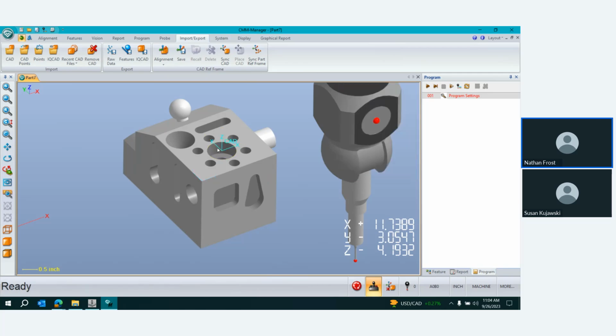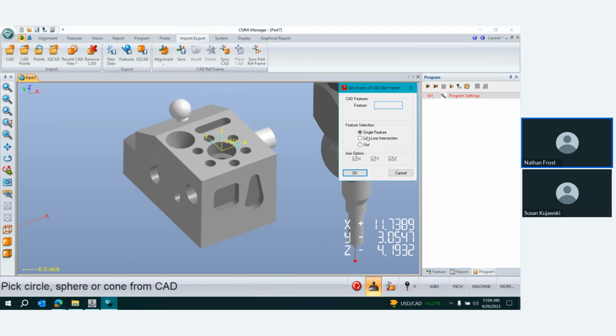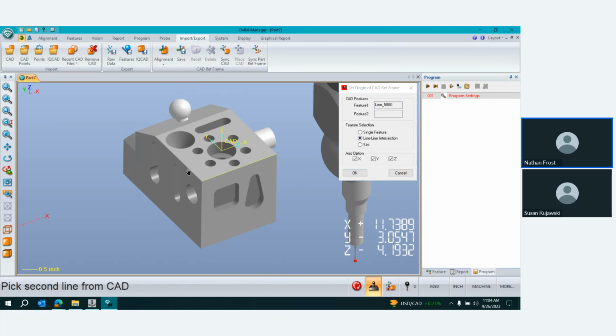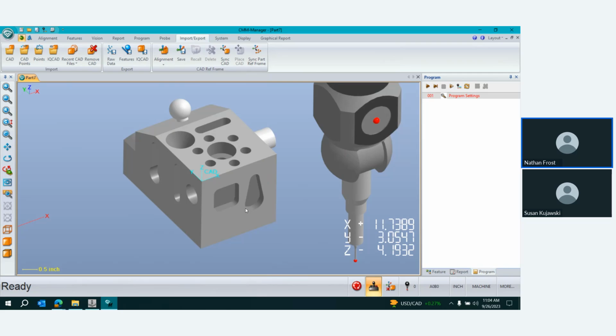So, the z-axis is going the wrong way, or maybe the origin's at the bottom of the part instead of the top of the part. You've got all kinds of tools to reestablish that coordinate system to your liking. So what would have happened, without these types of tools built into the metrology software, is you would have to go to your CAD designer and ask them to give you another copy of that CAD data that has the origin in your specified location. By having those tools here, it just empowers you to manipulate the CAD to your liking before you start with the measurements.